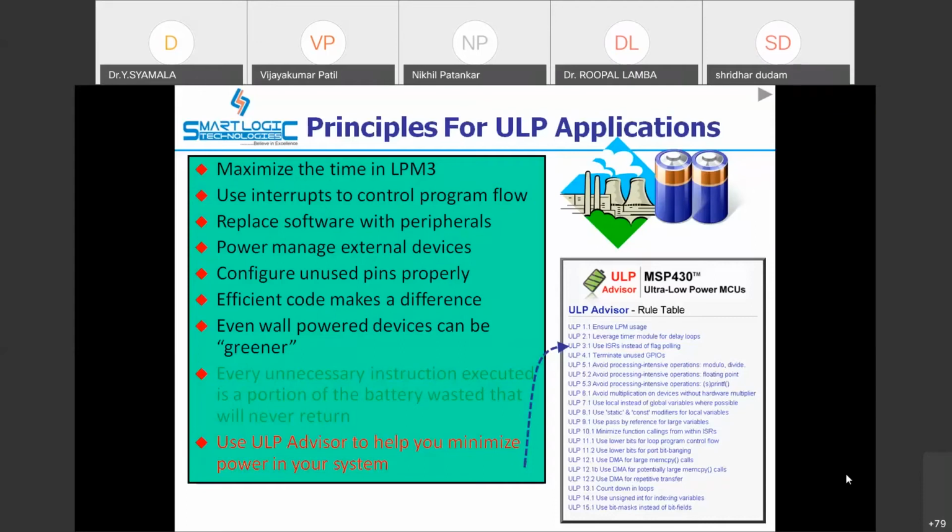At that time, you must take care of how to tackle the power required for the LCD. Much of the power required by the LCD is because of the backlight. So try to shut down the backlight if we are not displaying anything on the LCD. That you have to take care of from the software part.